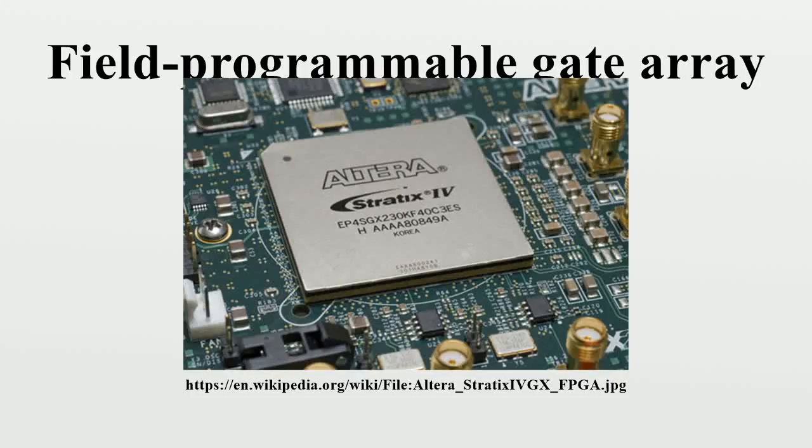A field-programmable gate array is an integrated circuit designed to be configured by a customer or a designer after manufacturing, hence, field-programmable. The FPGA configuration is generally specified using a hardware description language, similar to that used for an application-specific integrated circuit. FPGAs contain an array of programmable logic blocks, and a hierarchy of reconfigurable interconnects that allow the blocks